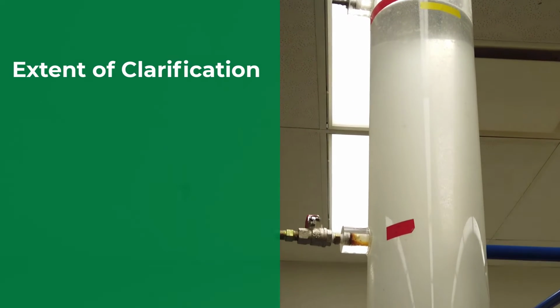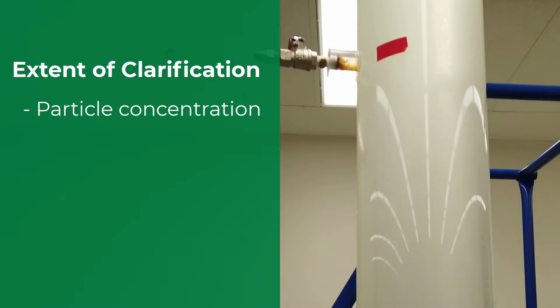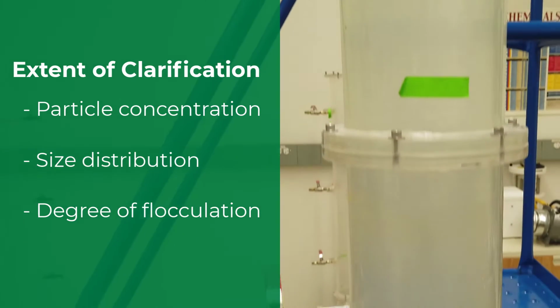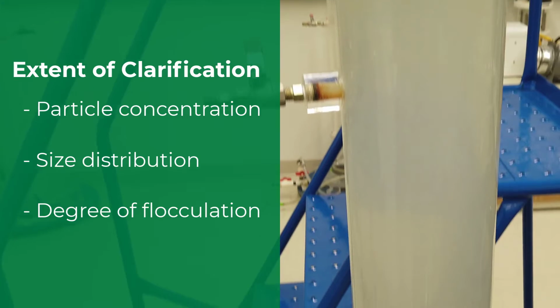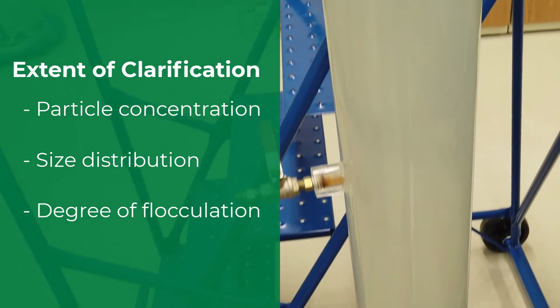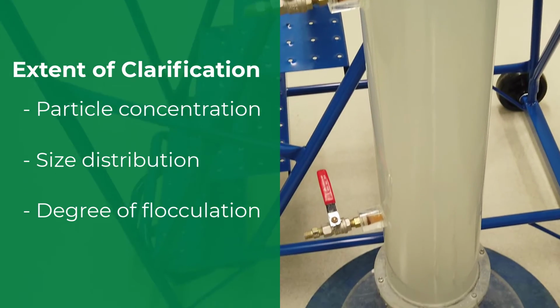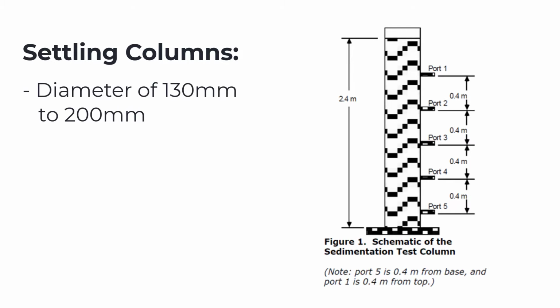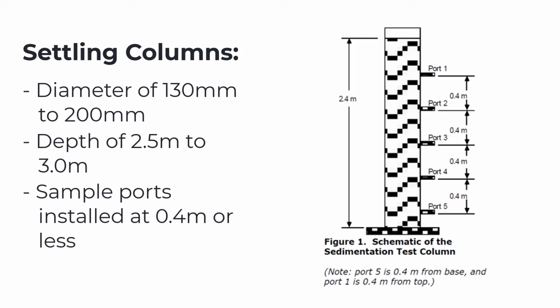The extent of clarification is determined by particle concentration, size distribution, and the degree of flocculation that occurs. The effects of these variables must be determined by sedimentation tests. The settling column used in these tests should have a diameter of at least 130 to 200 millimeters and a depth of 2.5 to 3 meters, with sample ports installed at intervals of 0.4 meters or less.